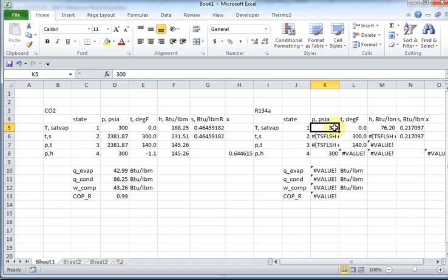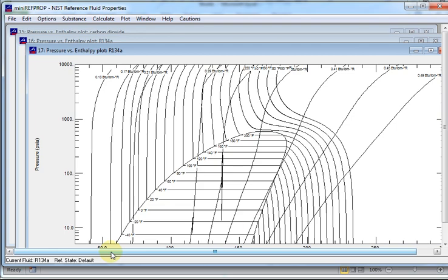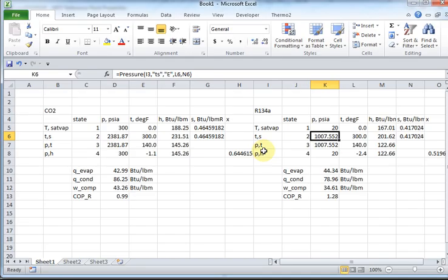So it's going to be 20 and 240. Oops. Escape. I needed to stay with temperature S. So let me do that. Let me go back to my plot. Okay, 0. I'm going to compress it isentropically until it comes out right in this vicinity, about 180. Looks like I'll go out to about 180. That's my guess. Okay. So let's go back to Excel, and temperature of 180.